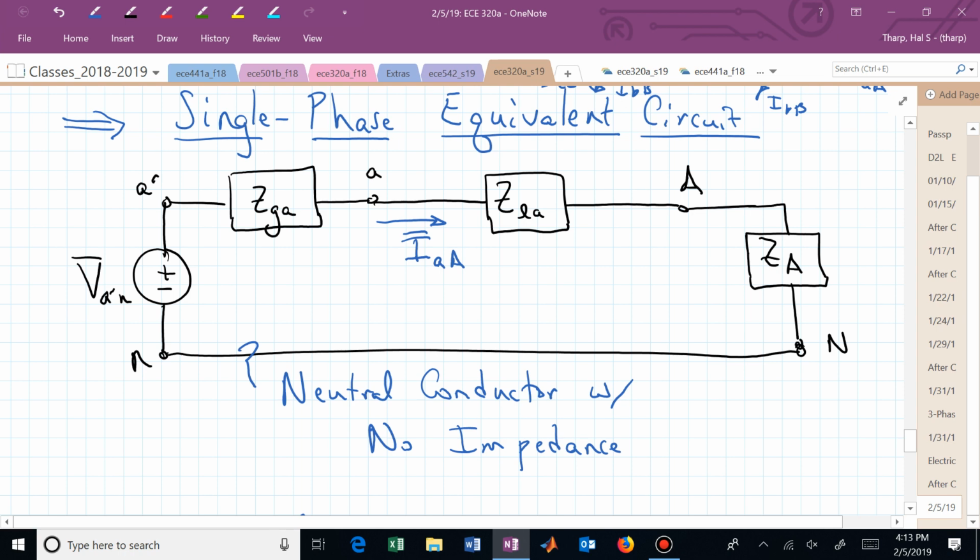We can do it on paper, and we can do it with analysis, and that's how we're able to solve these problems, by assuming that everything is balanced. But I wouldn't want to put my life or your life on the line by saying, he said there's zero current, let me just touch both terminals. Not a good idea, because somebody might have knocked an impedance out of whack, and now you're really flirting with disaster.